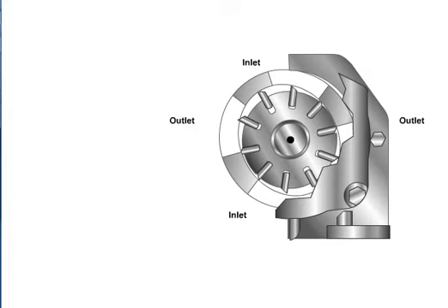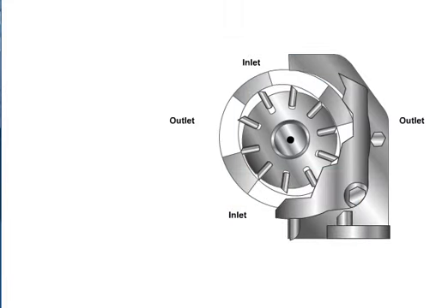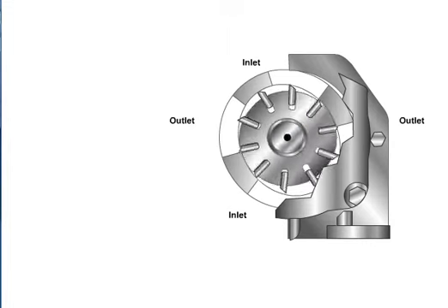This results in side-loading the shaft while under high pressure conditions. To compensate for this, the ring in a balanced vane pump is changed from circular to cam-shaped. With this arrangement, the two pressure quadrants oppose each other. Two ports take fluid in and two pump fluid out. The two inlet ports and the two outlet ports are connected inside the housing. Because they are on opposite sides of the housing, excessive force or pressure buildup on one side is canceled out by equal but opposite forces on the other side. With the forces acting on the shaft balanced, the shaft side load is eliminated.